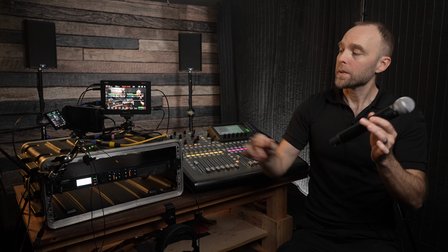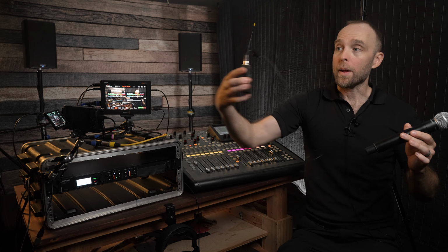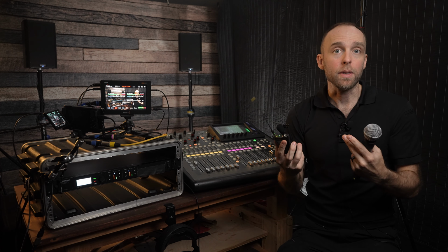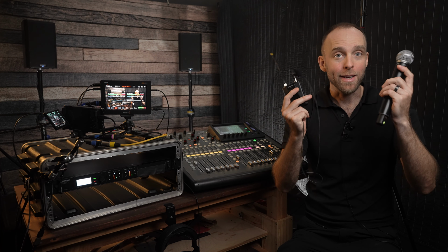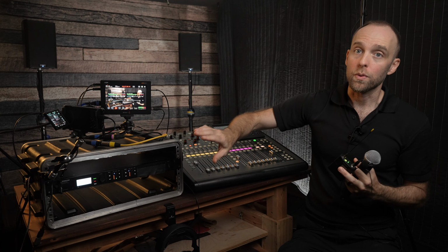The difference is that with wireless mics, be it a handheld or a pack with a lavalier like I'm wearing, the first preamp is actually in the pack or the transmitter itself, which these days can often be controlled from the receiver like this Shure ULXD unit. So when using wireless mics, we have to use the meters and gain stage on the receiver before we ever get to a console.